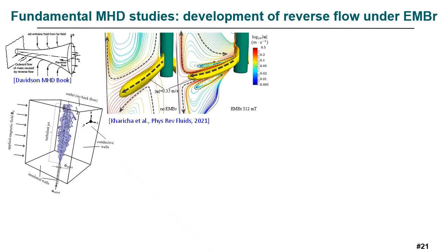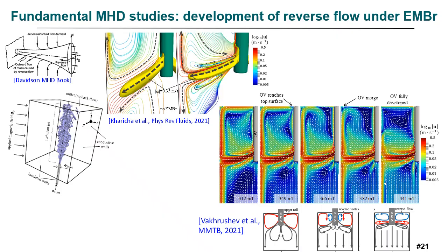For example, we have researched the restructuring of the submerged nozzle jets or upper and bottom rolls under the applied magnetic field. These results were assembled based on the intensity of the applied electromagnetic braking to predict when the secondary or ternary MHD structures can be formed.